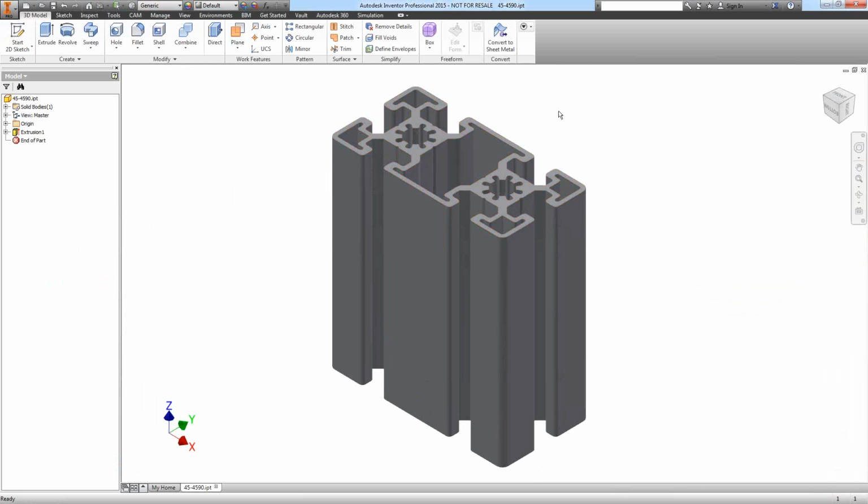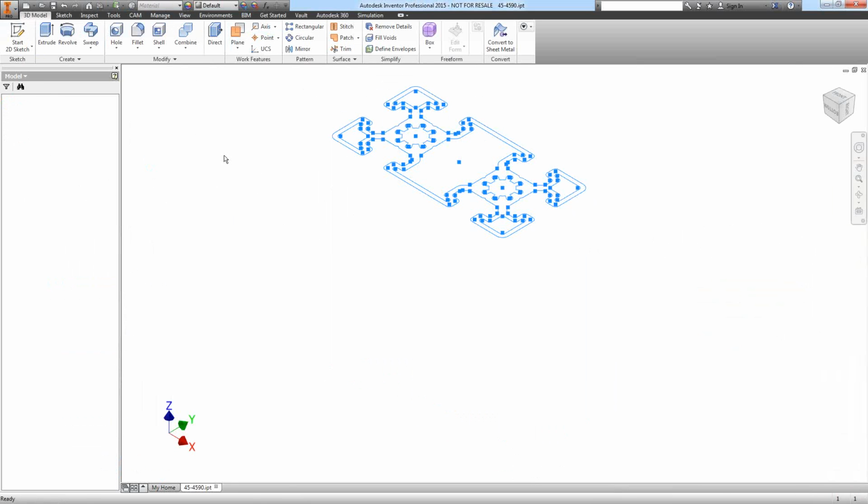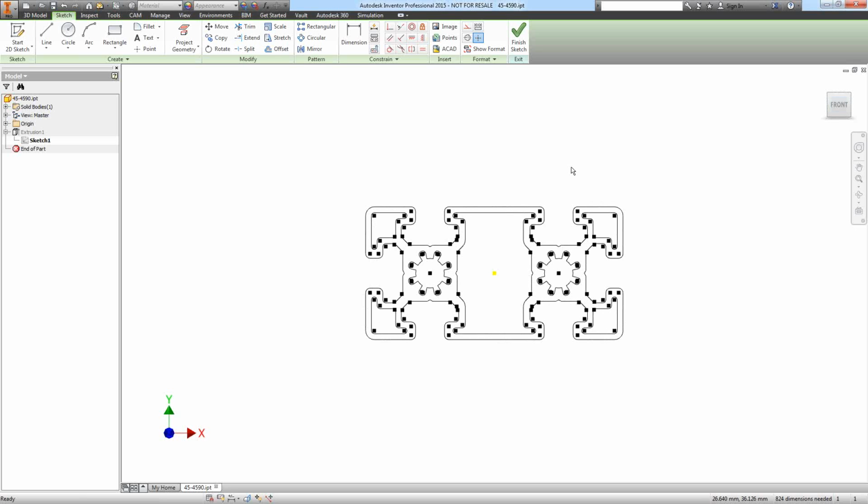This is something I downloaded straight from the 80-20 website. It's the 45 series family. And I can use this part to start with to create my shape. Now, I ultimately need some parameters to map to some of the category parameters. The model from 80/20 is just a sketch. There are actually no dimensions. So I am going to put in a few parameters here.